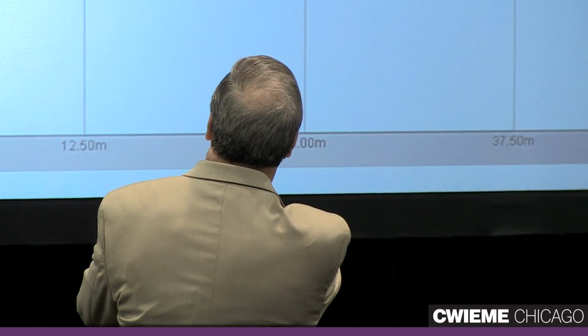And let's show you one more. Here's the 11th harmonic. How do we know it's the 11th? You can count them, right? I'll let you do that. It's about 5.5 amps RMS, and it's at 0 degrees. So it's starting right at 0 at time t equals 0. Now let's do something interesting with these 3 harmonics, the 5th, the 7th, and the 11th. Let's add those guys together.